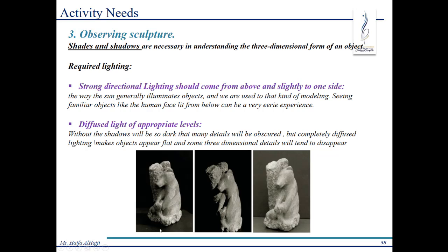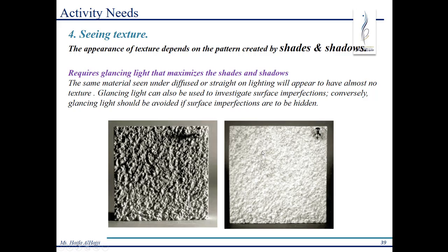You should put it somewhere between the right side of the shot and the camera view, almost at a 60 or 30 degree angle from the camera view, to give the effect of shade and shadow of the sun on the building and show its 3D characteristic features.